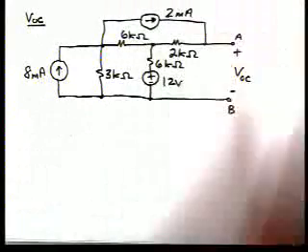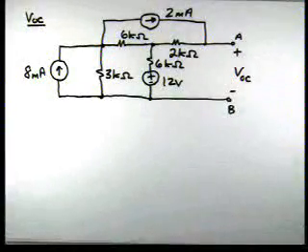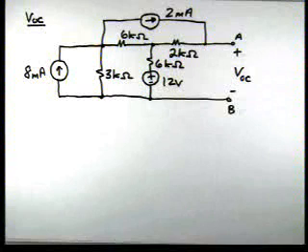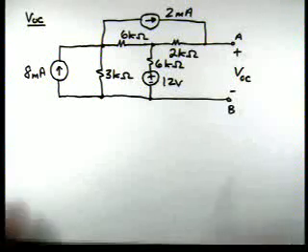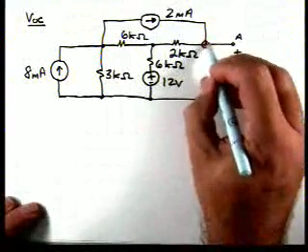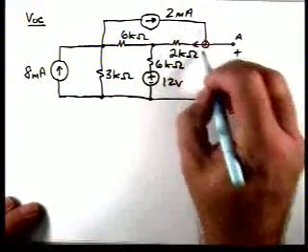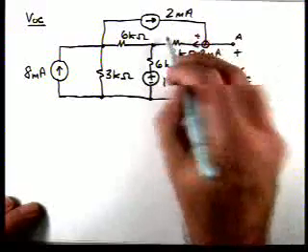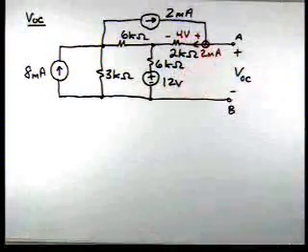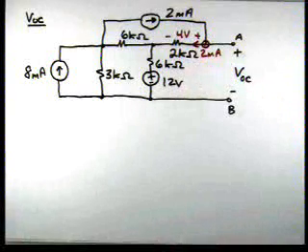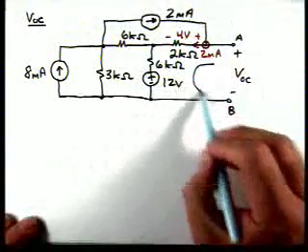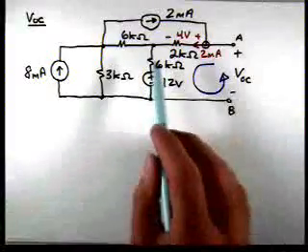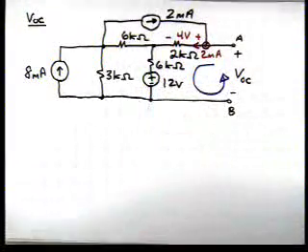So if we remove our 1K load, that is the resulting circuit. We've removed the 1 kilo ohm load. We've labeled the terminals A and B. We're now going to find V open circuit. If we make a few quick calculations, we know that current is 2 milliamps. So we know that voltage is 4 volts. Okay? So really, if we're going to find V open circuit, looks like we're going to have to use this loop. So we need to find the voltage from here to here.